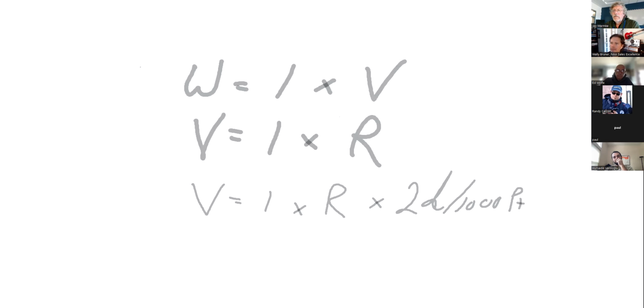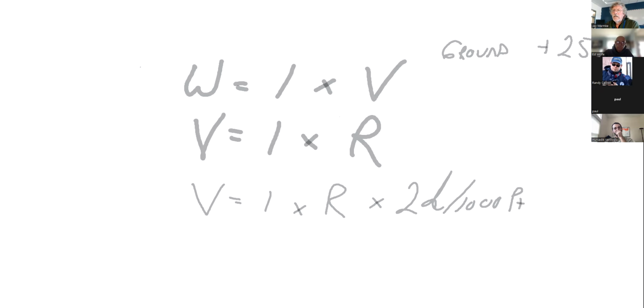So for a ground mounted system, you add 25 degrees Celsius. For a ballasted system on the roof, you add 30 degrees Celsius. And for a flush roof mounted system, you add 35 degrees Celsius. So those things you just have to know. Where that comes in is you add that to the ambient air temperature.